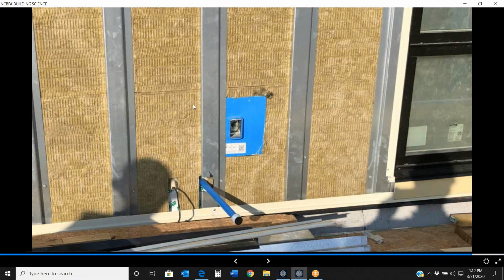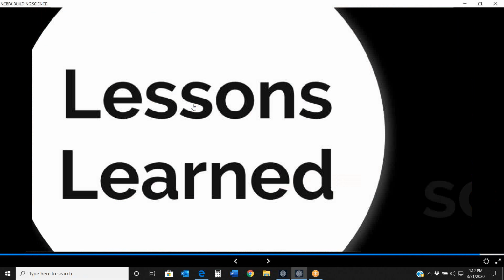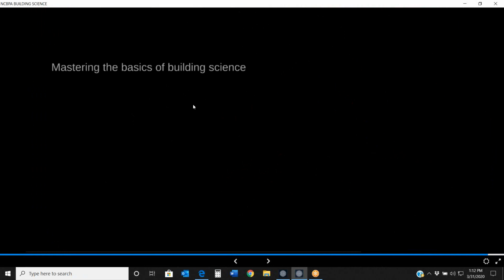Another one here is this one, and it was just the concepts. The materials were there, but the concepts weren't. The flashing device got installed outboard of the insulation and not tied back in to the WRB as it had been drawn and designed. So getting those points across.